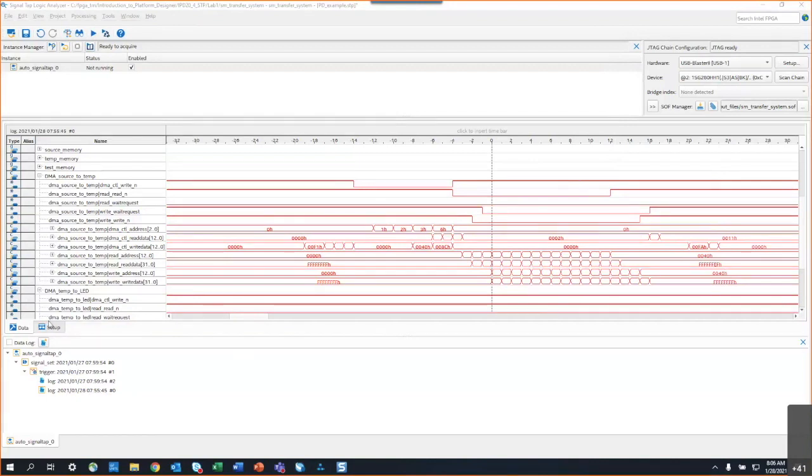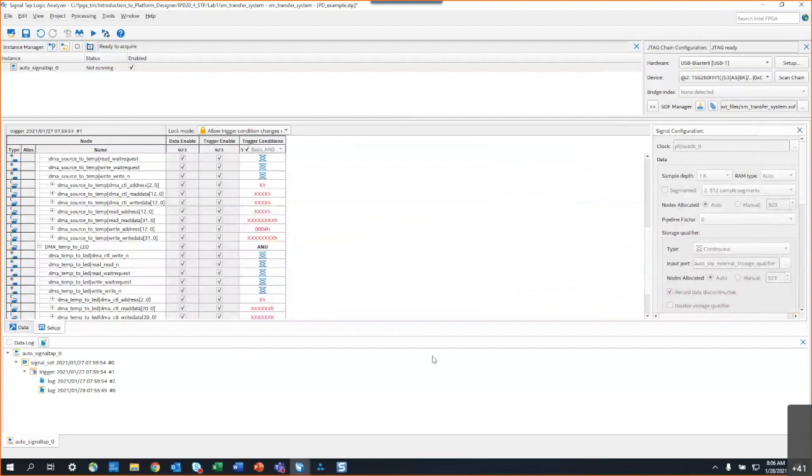And I have a FIFO write and read enable signals such that I write data 8 words into the FIFO and read it 8 words a few clock cycles later. And then the write and read sequence repeats continuously. Sometimes the ADC data and the input data to the FIFO are different as displayed on the traces on SignalTap. So what could be wrong?